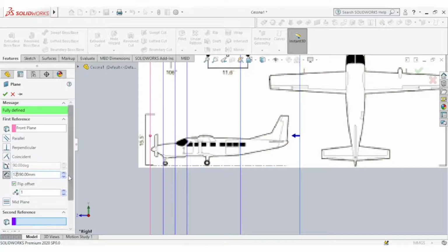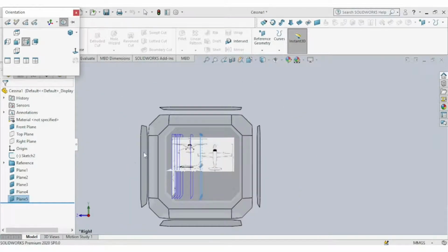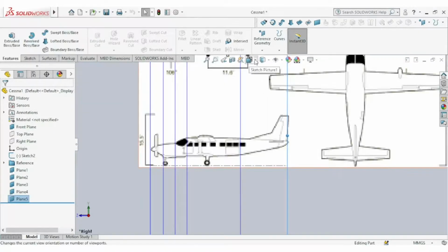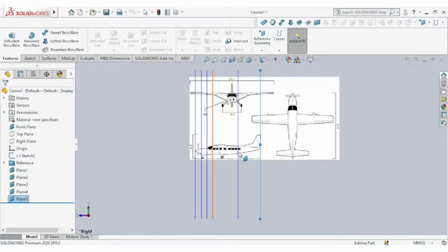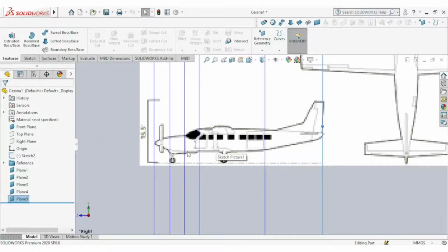In SolidWorks, I'm able to generate this view, the side view. We'll just explain that briefly. You can press spacebar and it will give you many options: left, front, right, top, and that. Or you can click on this drop down. Now I'm using my scroll wheel to zoom in and out.